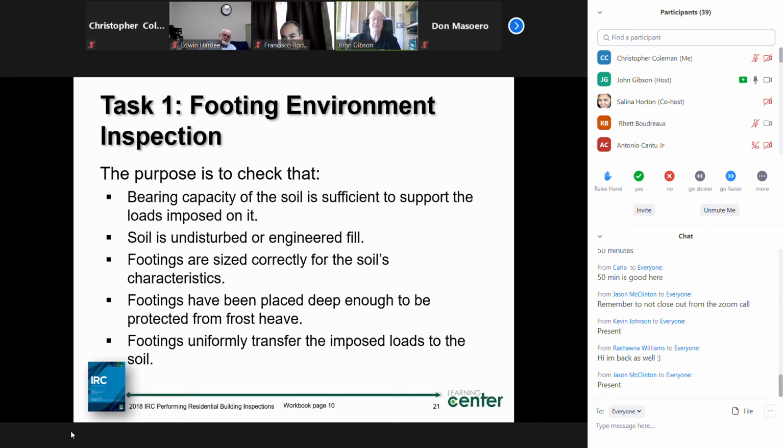And the first thing we have to look at is this idea of where is the grade plane? Now, the grade plane is supposed to represent what's considered the average grade around the building. And so we look at what's expected for that ground surface, which isn't the highest points of ground that we push up against the building. So I got it sloped away from the building on all sides. And we're not going to take up here where it meets against the building. And we're not going to take way down here. We're going to take a point that is within 6 feet horizontally of each wall.